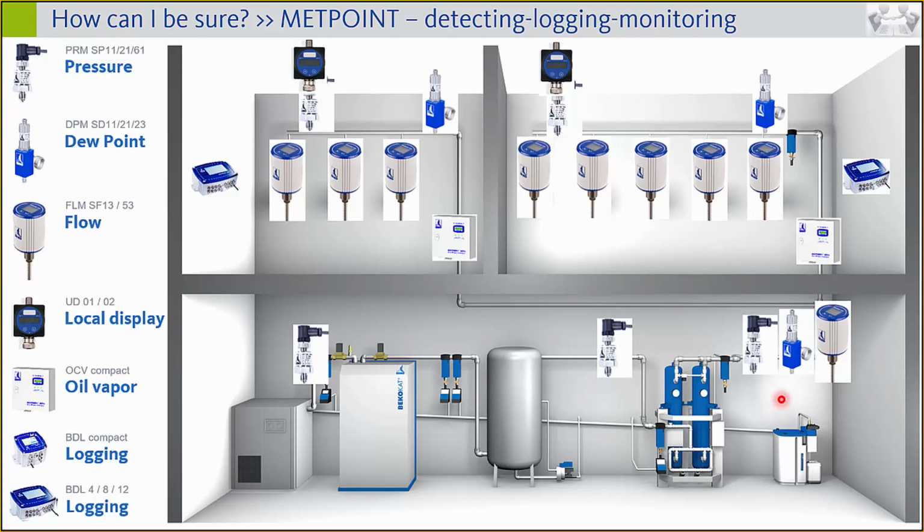Yes, so finally, also here, a data logger should be integrated. This data logger will automatically give you a recording of these detected values, and you can also pick up this data from the data logger if you have access to a customer network, for example. So far, that's the integration of some measurement equipment in terms of quality issues and cost estimation here in the customer's area, and for performance and troubleshooting issues in the compressor station.